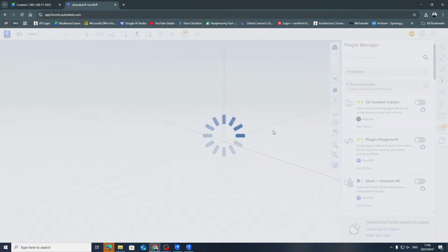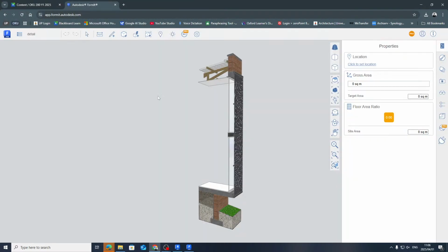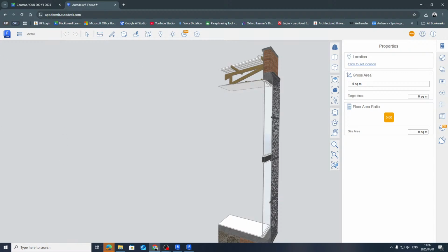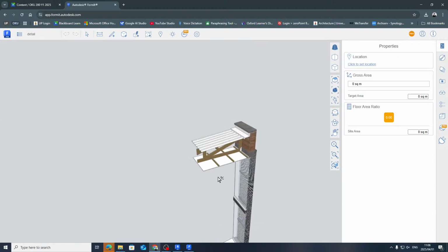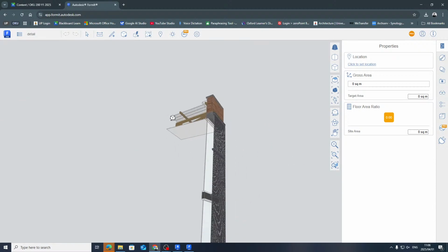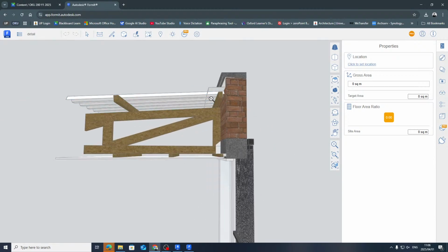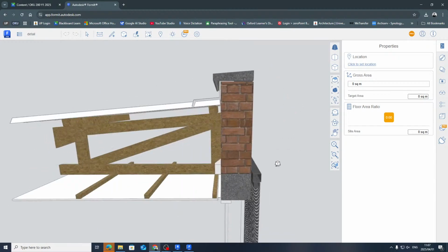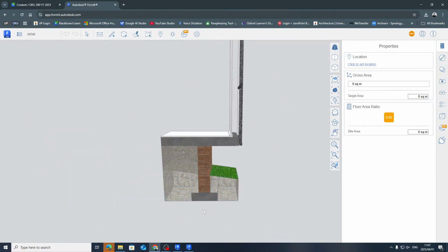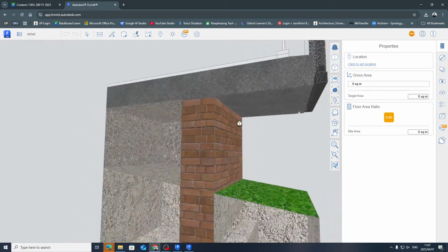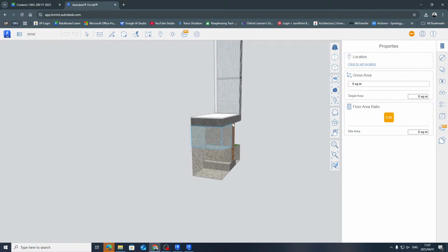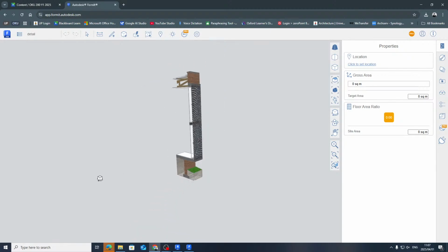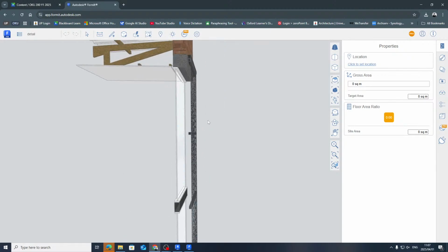So basically what we will be doing is building a detailed section. The whole series of workshops was leading up to building these detailed sections through the buildings that you're busy designing. You'll see that these are quite detailed, in how I've used the brickwork. You can do quite nice little details. Then this detail you plug straight into Revit and document it in Revit.